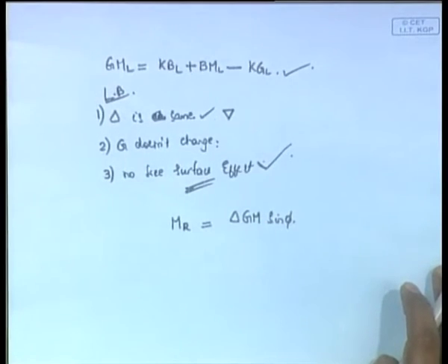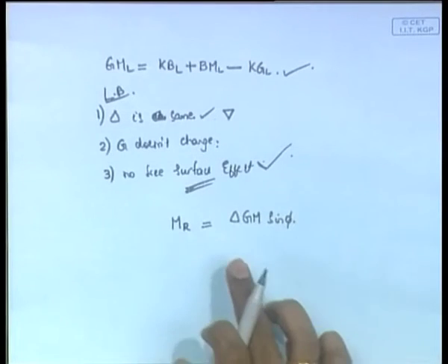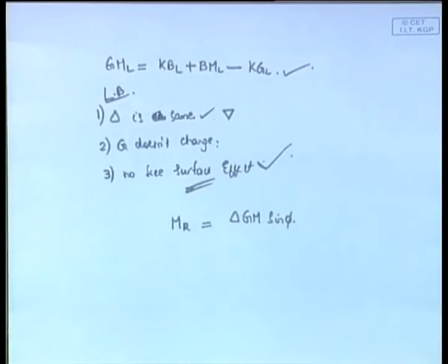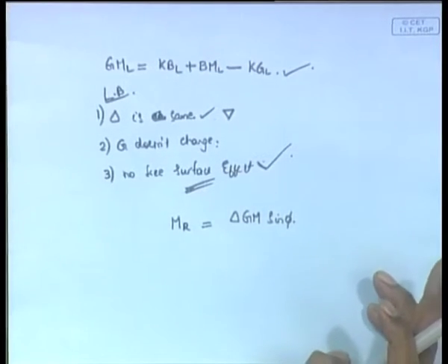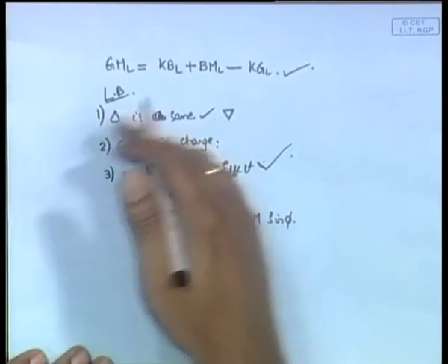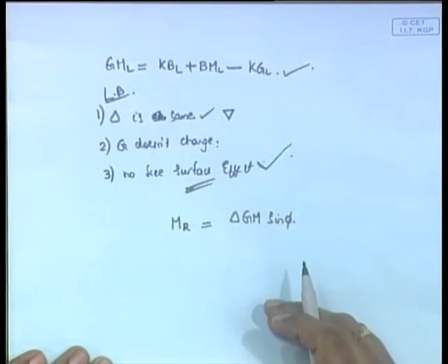Now, just look at the text, you will see that they have done it for a box shaped barge with given values of L, B, T, etc. They do it using the two methods of added weight and loss of buoyancy, and they get exactly the same righting moment. But you will get the same only if you do this properly, meaning you take the free surface effect in one case, you do not take it in the other case, and you take the displacements properly. This is the way in which you solve the case of loss of buoyancy.